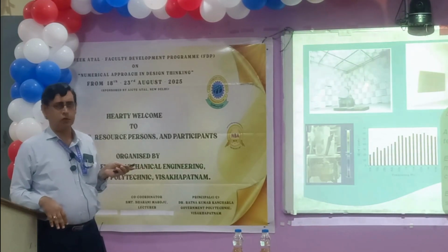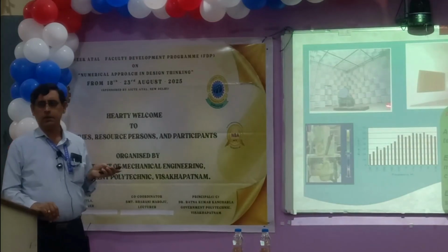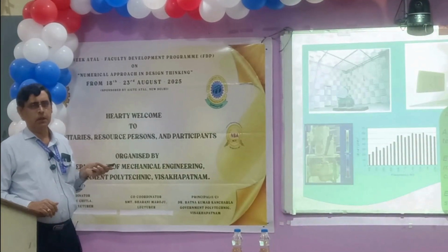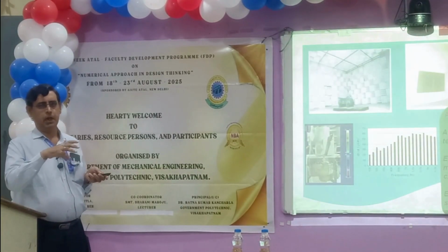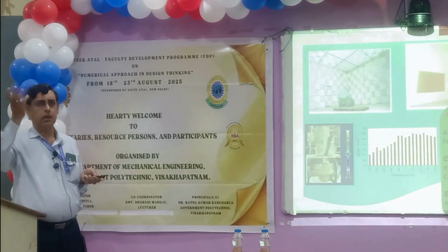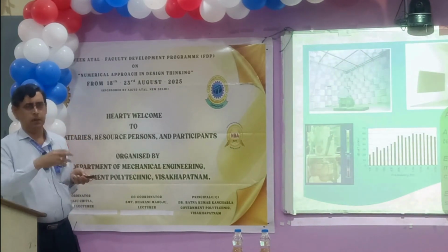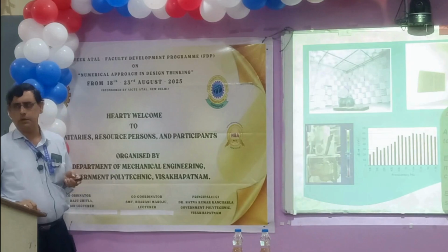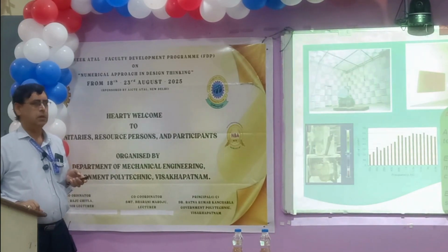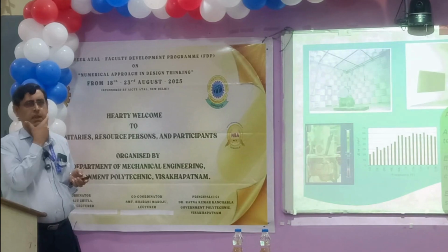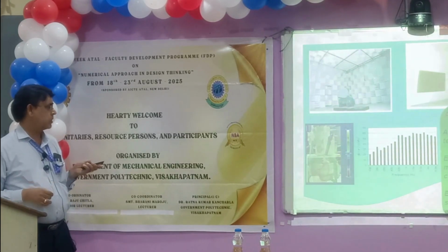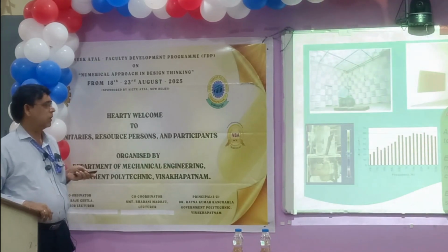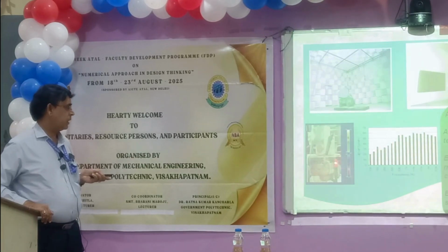That's why this is as per the ISO 3744 we call it. As per that standard, we get the measurements in a big facility like this. These facilities are very unique. NSTL has one. Similarly, there are NPL in Delhi and Chennai and Kochi. They have this facility, and Pune also. ARAI, automotive station also they have. So very few facilities, 5 or 6 facilities are there in India. So they can be utilized for research area also to do research on sound and noise, etc.